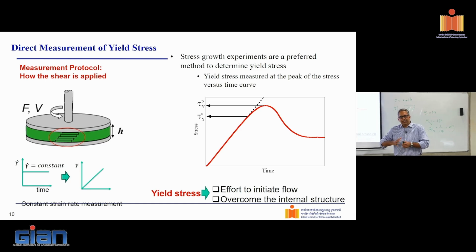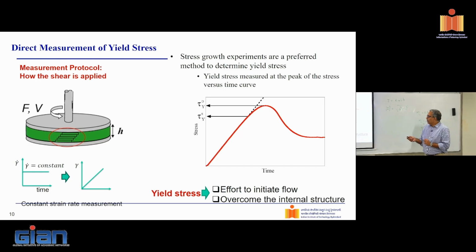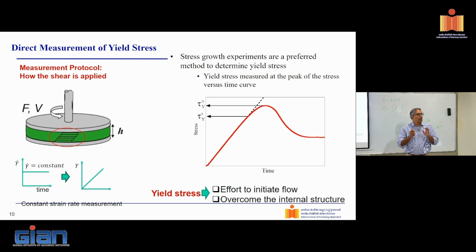When I try to shear it, I'm getting almost linear increase in shear as I'm increasing the total shear angle. It's behaving like a solid. That's what this linear part is. And this point at which it yields, beyond which is where the flow starts. So this basically becomes the point at which flow is initiated in the liquid, right?